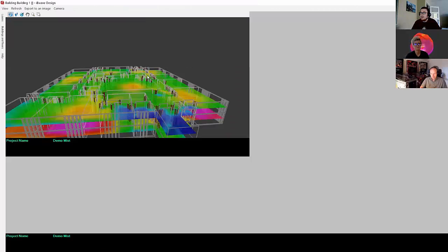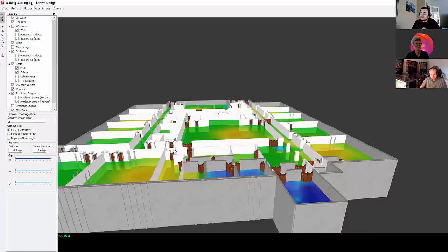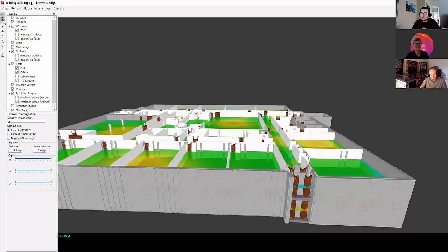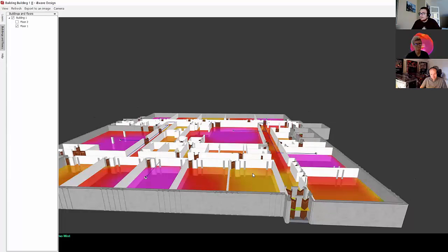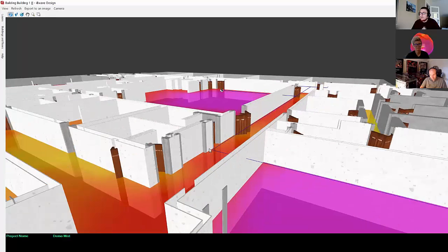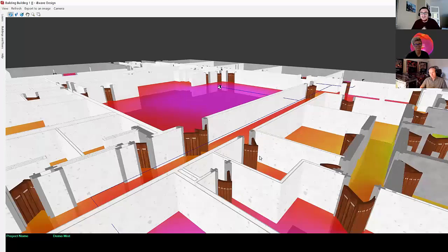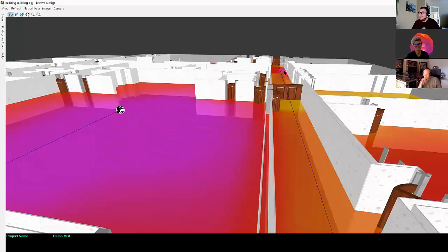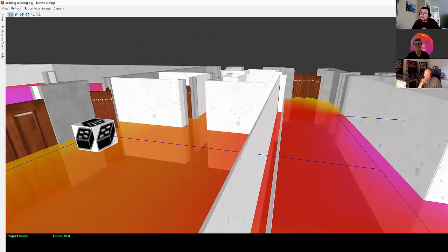And I could see that in 3D, right? So I could impress my customer and say, oh, here's your building, here's the coverage you're getting inside your building. Now if I go to just floor 1, the one we were focusing on, this is the coverage on floor 1. This is where we're going to place the APs. This is where the cable will run, and we need to drill a hole here. Sorry, but this is necessary. And then you could go inside and see where your equipment room is, and this is where the switch will be located. And that's the wow effect of iBwave.